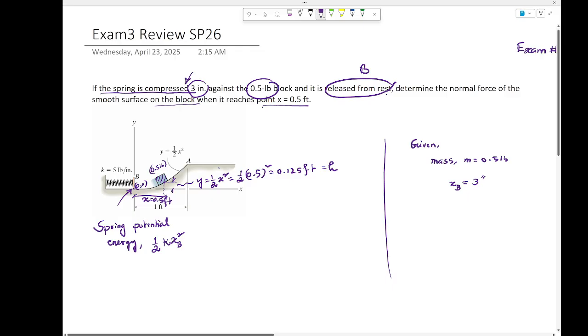Yeah. Pound mass. Okay, so you can still say like 0.5, and in that case you gotta write m here as a subscript. But if it is a load or the force itself or weight, whatever way you want to say, then you should be writing pound force, lbf. Okay, but again, if I'd like to get the mass in slug, you have to divide it by 32.2. Okay, that's the relationship. Anyway, so xb is the spring compression. You may want to put some note here next to it, right? So spring compression.